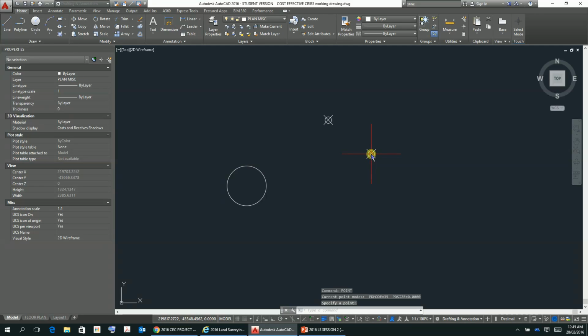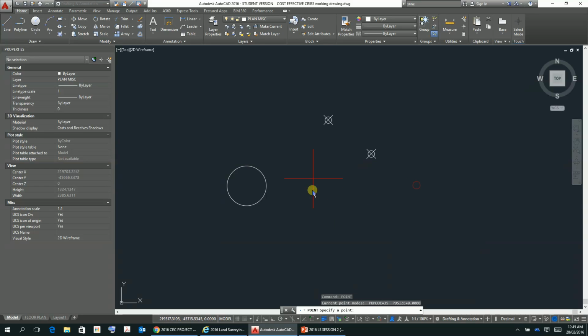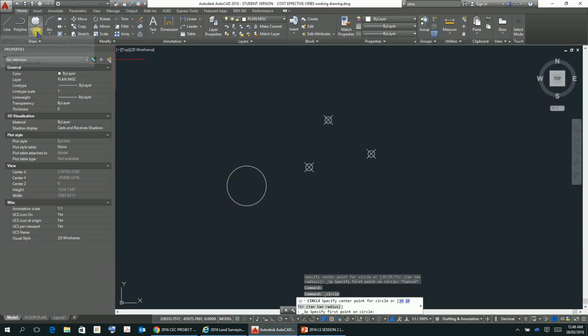And there is also a way to draw multiple points. So you've got that, and then let's put a point over here. So if I want to draw a circle between those 3 points, I can just go circle, 3 point. Oh, now I need to turn on my snaps, so it will snap onto those points, which, by the way, the points are nodes, so that's turned on.